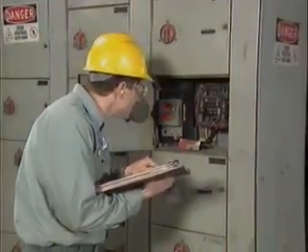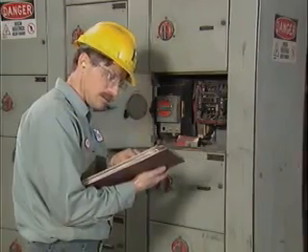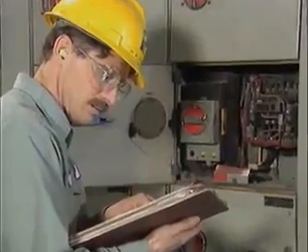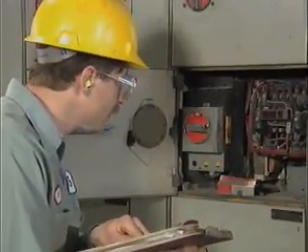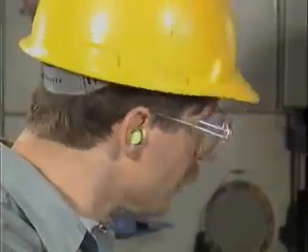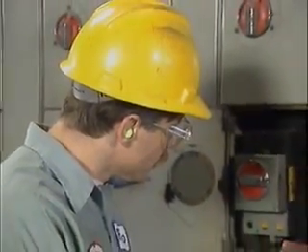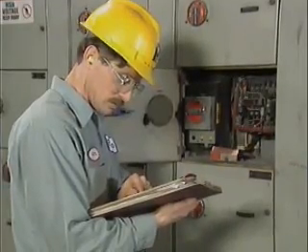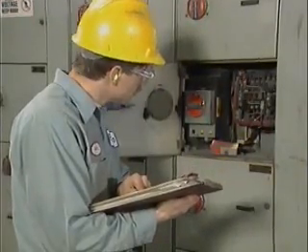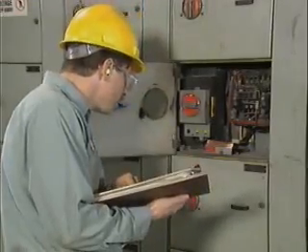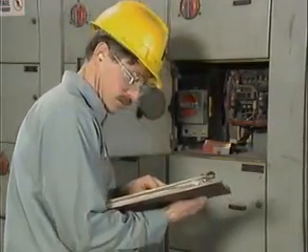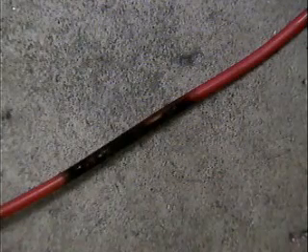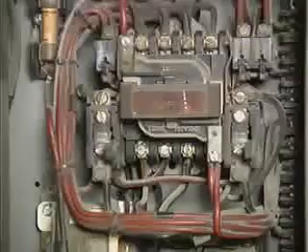After the possible causes of the controller malfunction have been narrowed down, the components that have not been eliminated should be carefully inspected. You can use the motor controller's wiring diagram as a guide to locate each component. During an inspection, it's important to follow all applicable safety precautions. You can usually begin your inspection by using your senses of sight, touch, and smell to thoroughly examine the controller. You should look for anything out of the ordinary, such as dirt, burnt insulation, broken wires, or loose parts. An unusual smell may indicate burnt insulation, and a hot spot may indicate overheating.